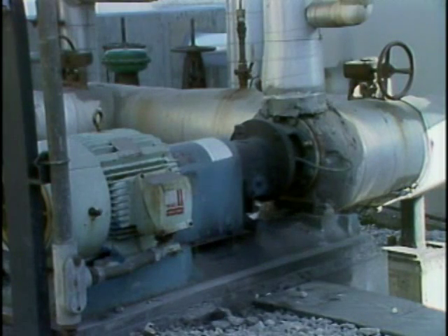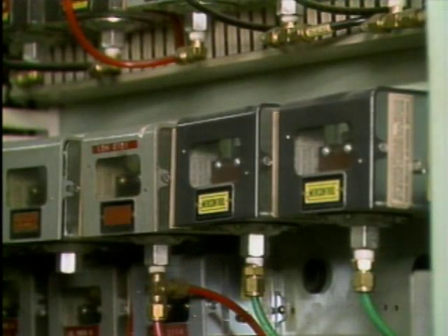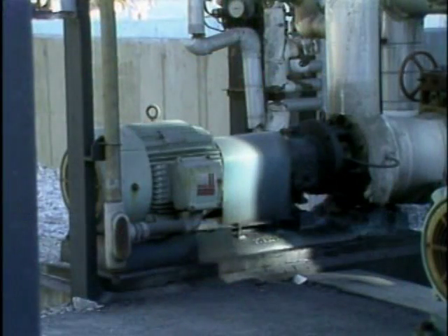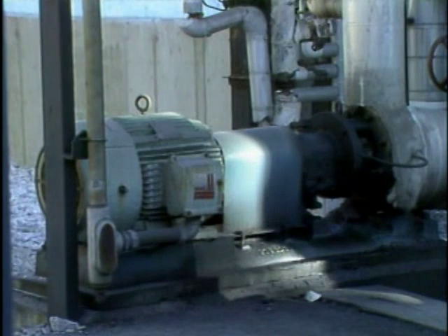For example, if this pump, which supplies water to a holding tank, fails, the water level drops to a point at which a switch activates the low-level alarm and activates a standby pump to help bring the water level in the tank back to set point. A switch may also be used as an interlock.